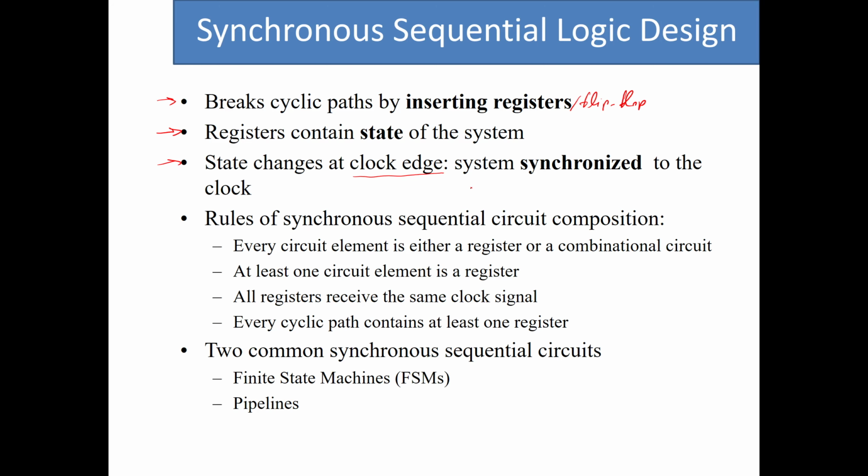That means that the system is synchronized to the clock, and that is basically the reasoning behind calling these types of circuits synchronous, right? Because the act of storing the state of the system happens at the clock edge for all the registers and flip-flops in the circuit. Because of that, we say that the system is synchronized to the clock.